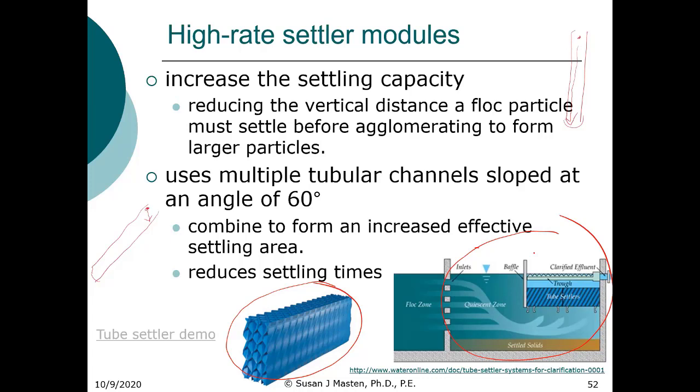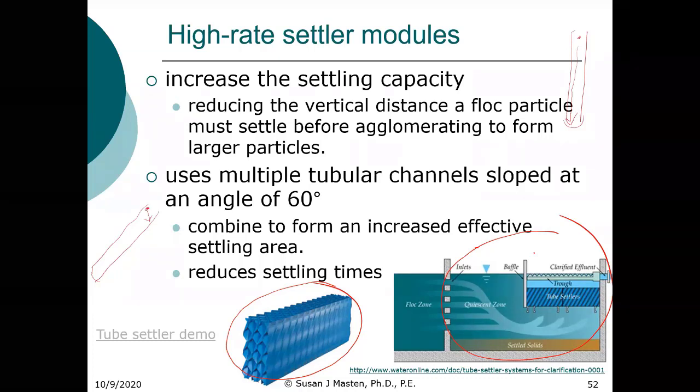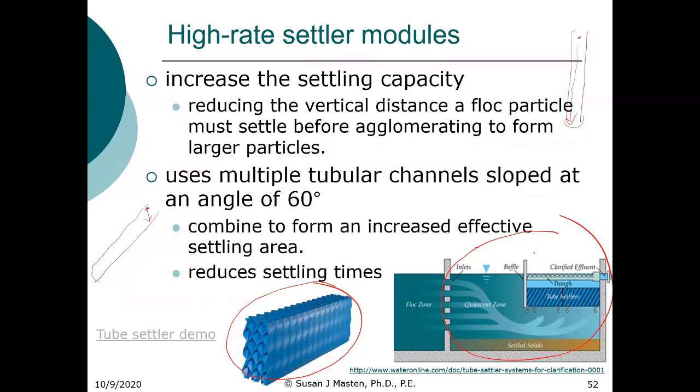Makes it less expensive. Exactly. It's less expensive both for the cost of the coagulant and the cost of sludge processing and disposal. So that has a significant impact. So you'll find that in terms of retrofitting, these high rate settlers are extremely beneficial.